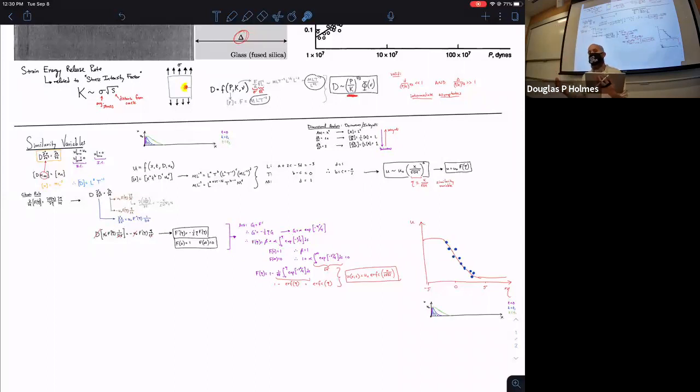I don't know if the concept of self-similar is confusing or it makes sense, but basically that concept of self-similar, we talked about that physical similarity where the crack looks the same, or the drag behaves the same as long as we scale up everything accordingly. This self-similar behavior is a way of saying we can collapse all of these curves onto one curve if we are plotting our things appropriately, if we find the right way to rescale our spatial or time domains. And if we do so in such a way that they fall upon each other, that's what's referred to as a self-similar behavior.